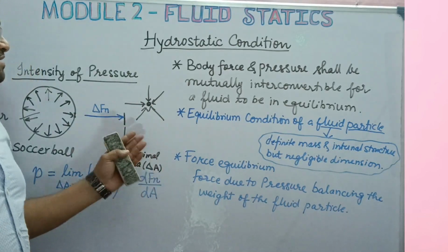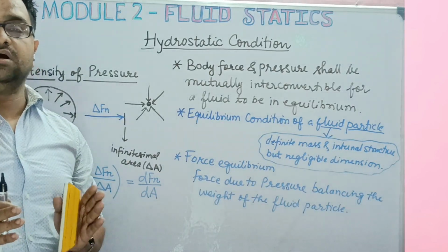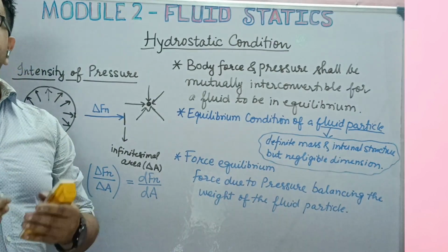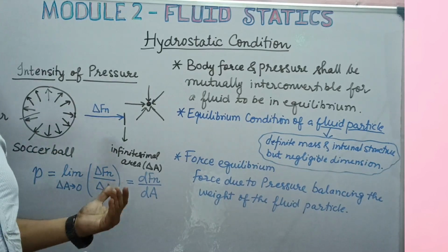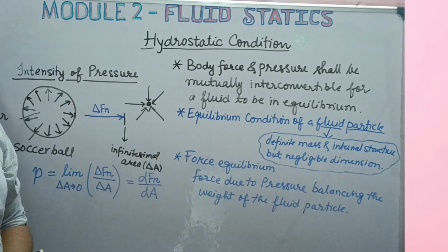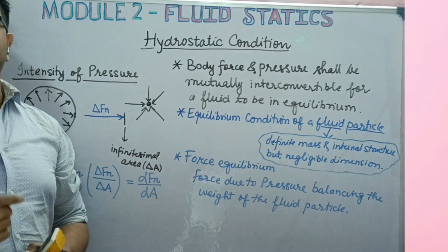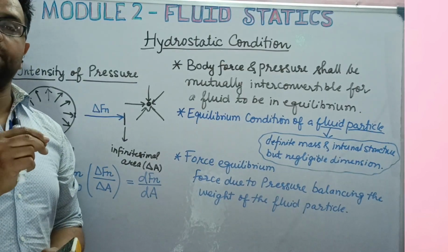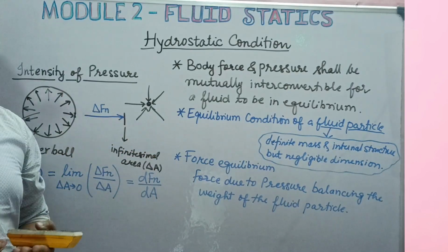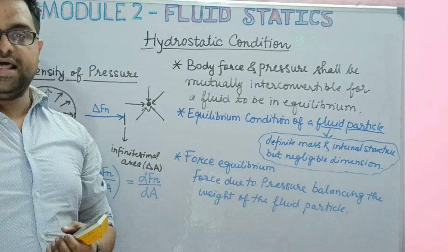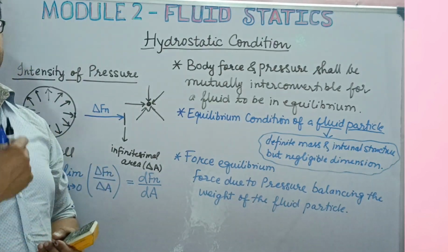So pressure is not a force. Pressure is not actually a force. It is a scalar that produces a resultant force by its action on an area. So we cannot say that pressure is a force. It is a scalar quantity that produces a resultant force that will be acting perpendicularly to the area upon which it acts. The resultant force is normal to the area, and it acts in a direction towards the surface, or a direction which is perpendicular to the surface.